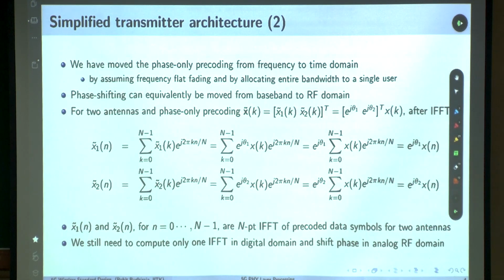Okay. There is no restriction on the number of antennas, because the number of antennas, when compared with an RF transceiver, is a very small piece of hardware. Right. Here, for each chain you require two digital to analog converters, one up converter, one power amplifier. Right. Okay. So this is how we are reducing it.